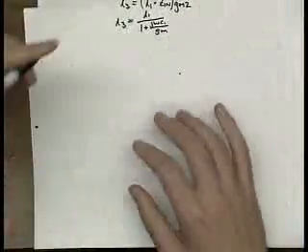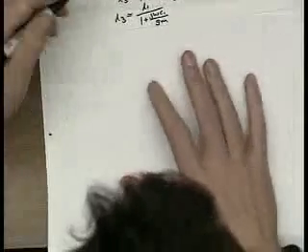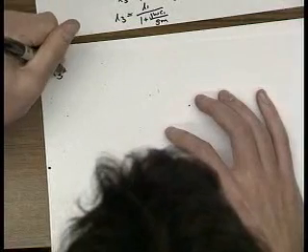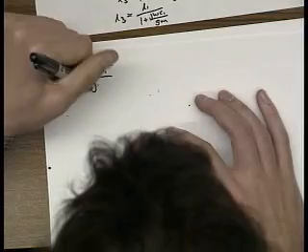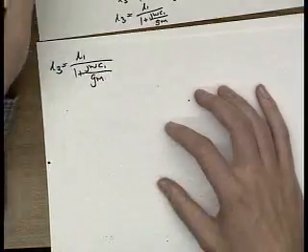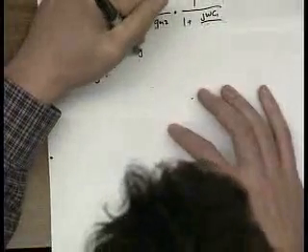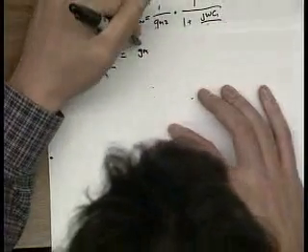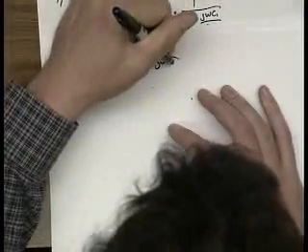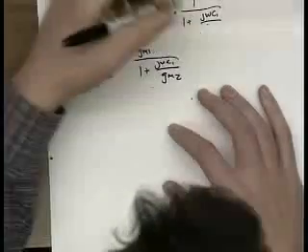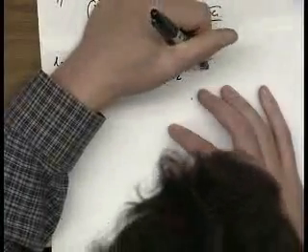Okay. So now, just to recapitulate, I3 equals I1 over 1 plus j omega C1 over Gm, which in turn, we already calculated what I1 equals, Gm VID over 2, equals Gm times 1 over 1 plus j omega C1 over Gm2 times VID over 2.